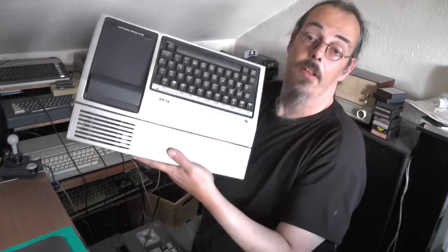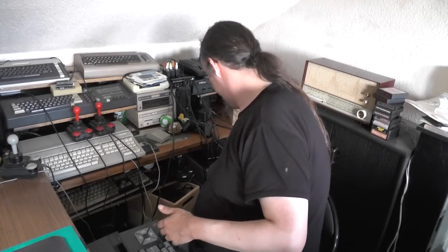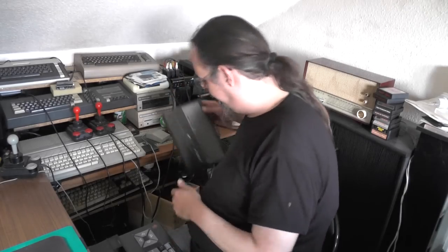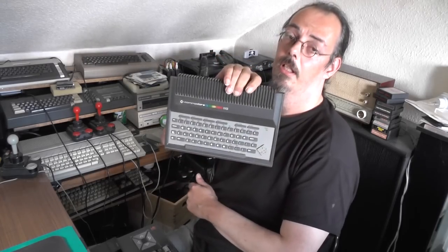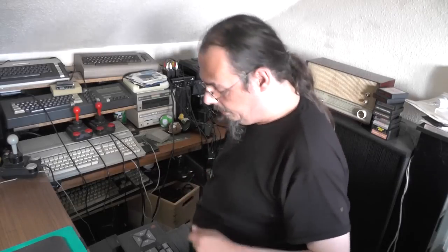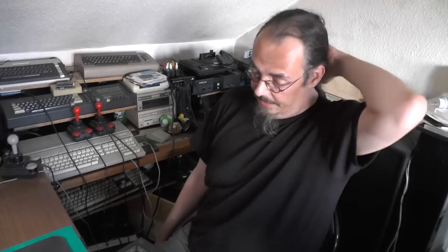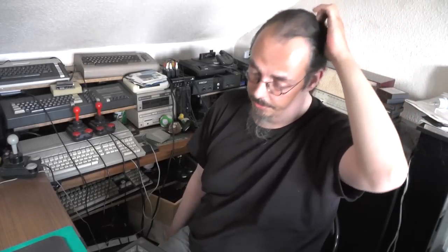Something fell. This one already was out of the market in 1984, and this is also an 8-bit home computer from the 1985 era. Not as good as the others, so I skip on that. Yeah, same graphics chip as the ColecoVision and the Texas and the Sega machines. 16 colors, 40 by 24 characters in text mode, 256 by 192 pixels in bitmap mode.